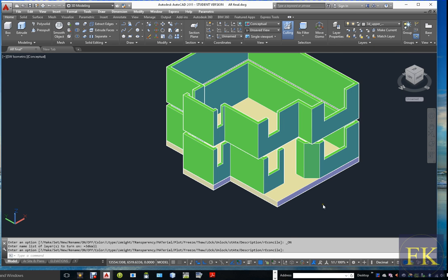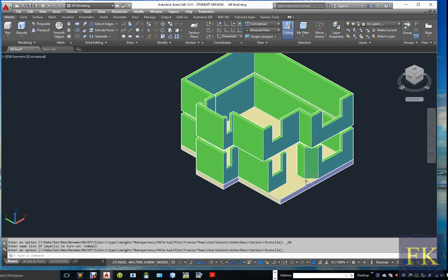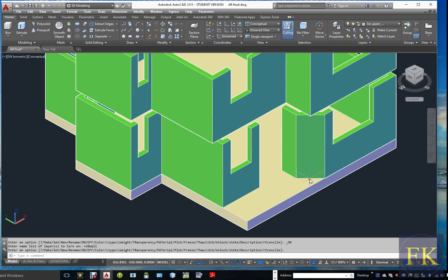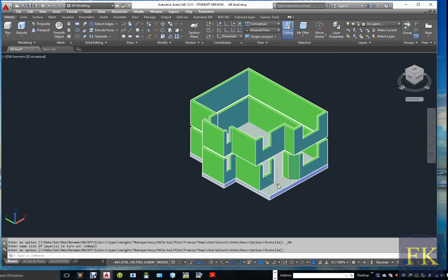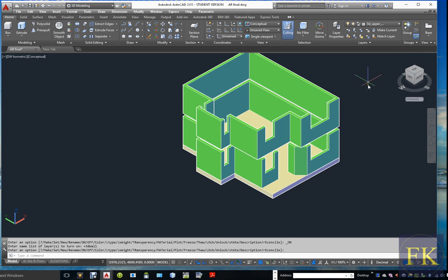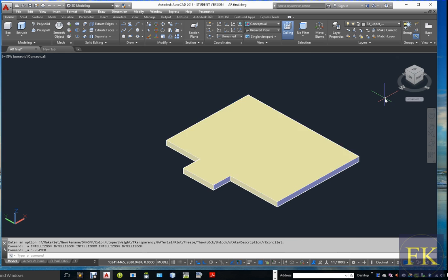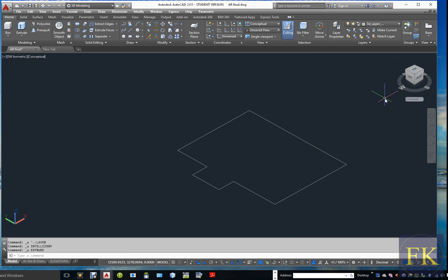Okay, let me turn on my 3D wall. Yep, technically we have to create the grade beam first and the slab, and unless you want to make a different texture on the slab, then this works fine. But if you say we want to create a different texture for the floor tile, then what we can do is, let me control Z, and then we can offset this.